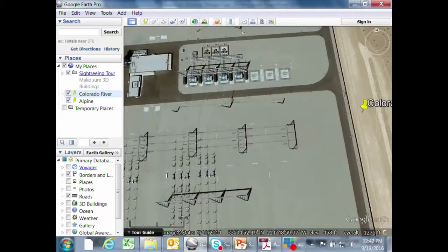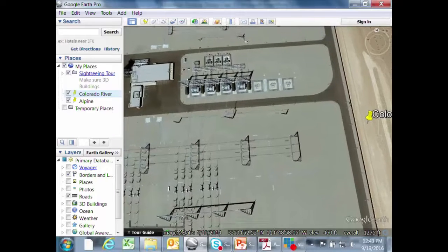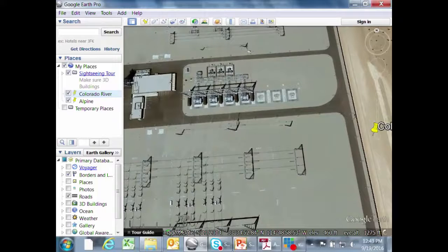These structures are, my recollection, about 90, 95 feet tall. And again, you have to span over the main buses. They put them just behind the transformers so that your jumpers drop down to the primary bushings. But on the secondary bushings, you have bus supports that train the conductors out, and then you connect up to this side of that. This is the tertiary bus. A lot of transformers actually have 3 windings, and Edison uses the tertiary bus to connect line reactors to, or not line reactors, just tertiary reactors.